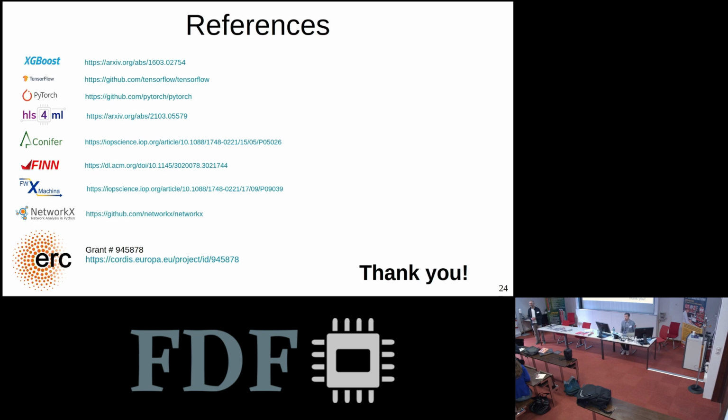I suppose it probably represents what the FPGA is first configured with, but what it might hide is, if you have a reset circuit, and you reset the design later on, but in simulation you've only tested the initialized values until you finish your test, you might find that certain values haven't been reset to the value you expect.